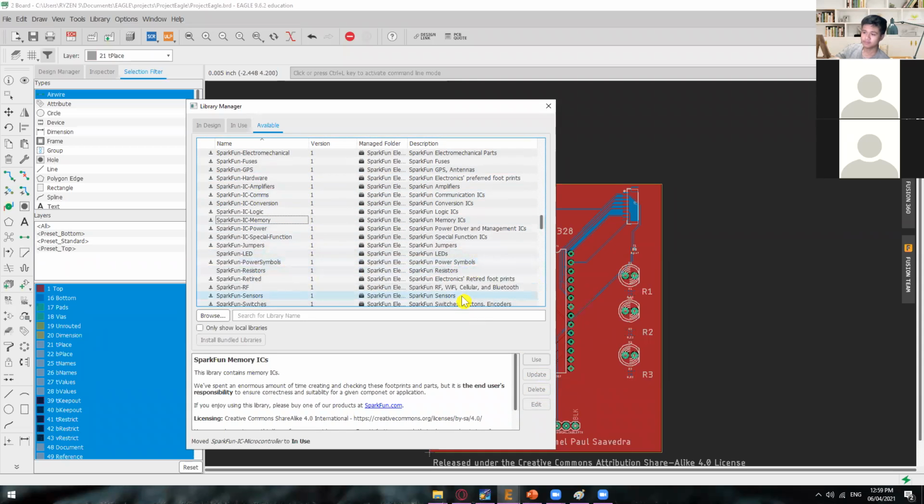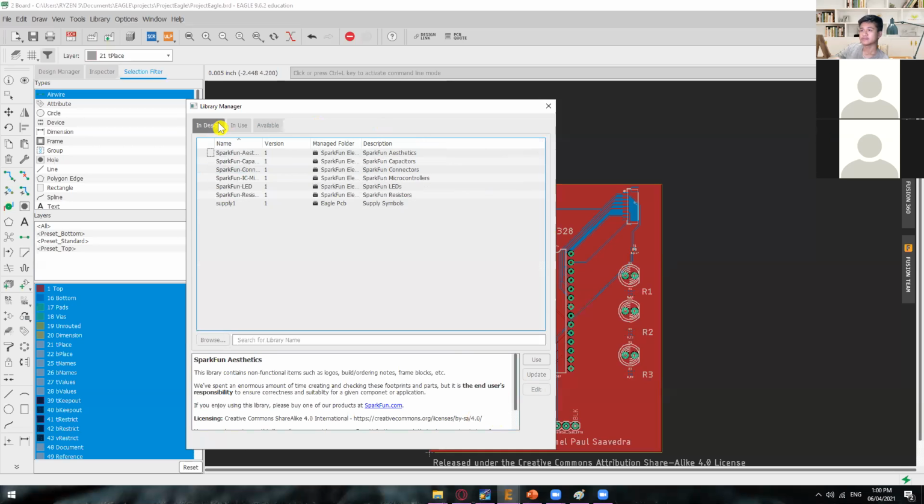Yes, sir. There isn't any, so let's try to use this specific IC. Sir, the specific IC, as long as the traces and the package match? Yes. So another way that you can do is use a generic microcontroller as long as they have the same design, even though the specific model is not the same. As long as they have the same arrangement of pins and the same dimensions, width and length, then that will also be okay. Okay, sir.